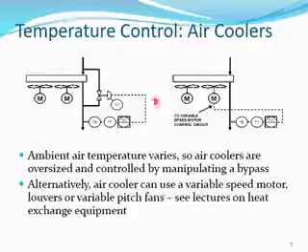We can control this device by two types. For example, control the rotation of the impellers, or control the flow inside the tubes. We can control the rotation of the impellers, meaning we can control the fan blades; the RPM can be increased or decreased. RPM is rotation per minute.